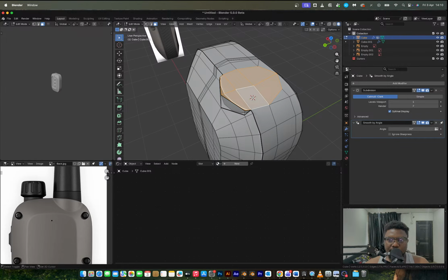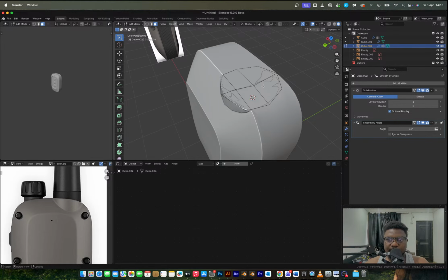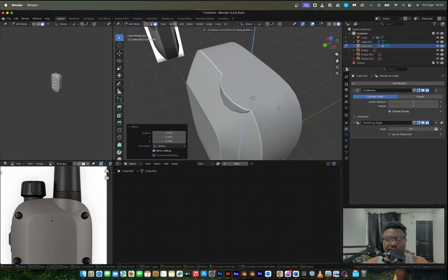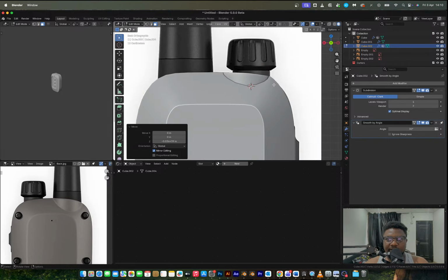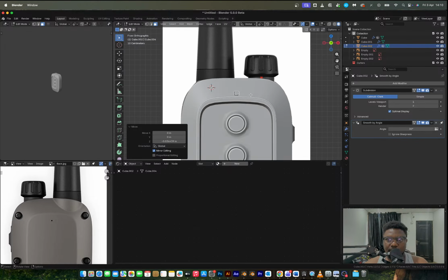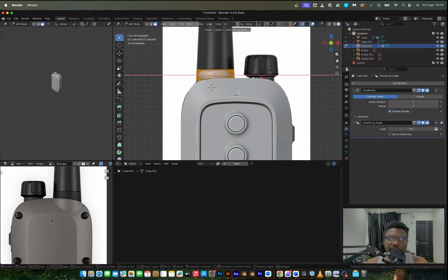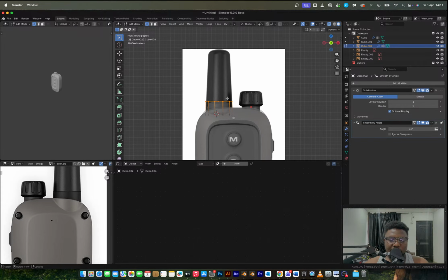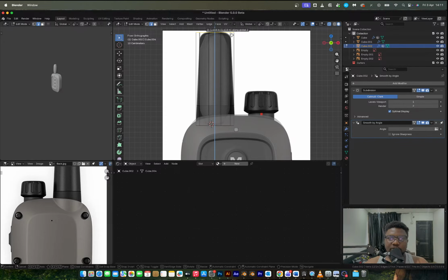Next up, I'm just going to go on to creating this shape. I think I'm going to start with duplicating this. This is definitely not a circle, so I'm going to turn that into a circle. Scale that down, GZ. And on the side right here, I can extrude, SZ0, extrude, S Shift Z. I'm going to select all of this, GZ, and then GZ all the way to the top right here.